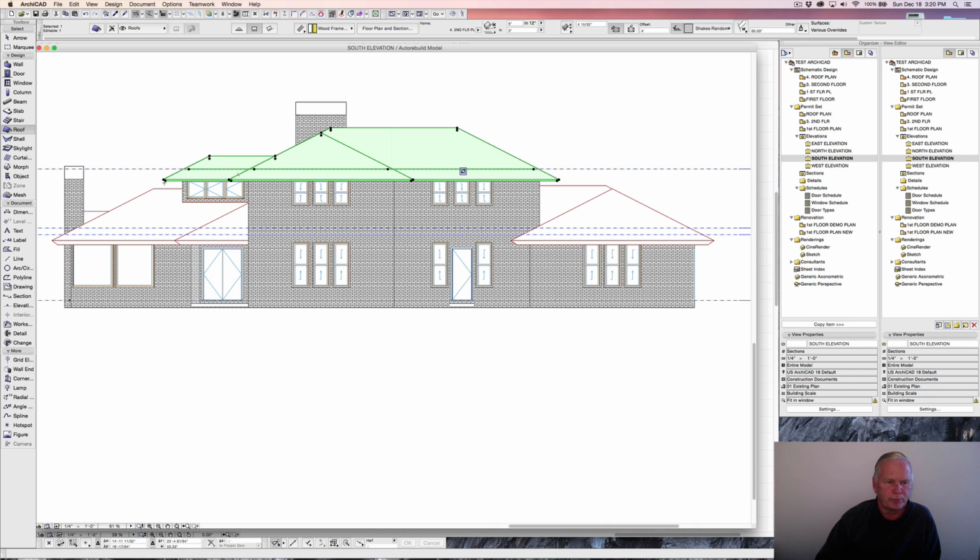and not have to put in a fascia and do it in that fashion, we're going to take this and change that structure, and instead of the 4 inches that we had it, we're going to make that 1 foot, and then that's going to basically throw the roof up and give us a fascia that matches the one on the first floor, which is what I want to have happen.